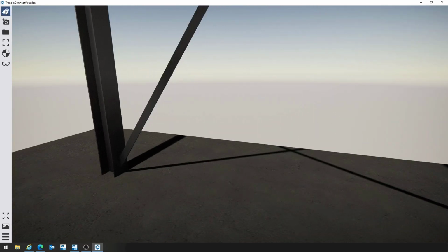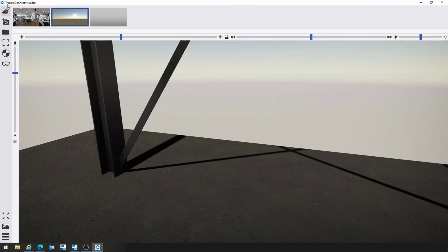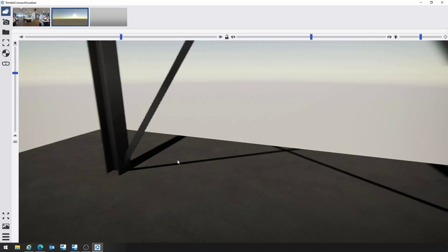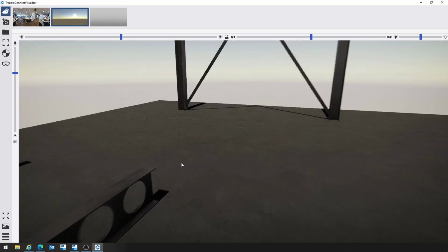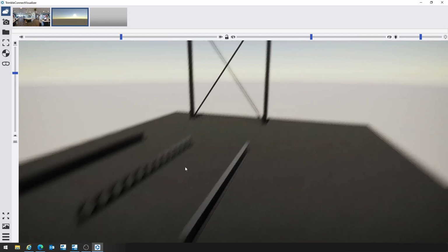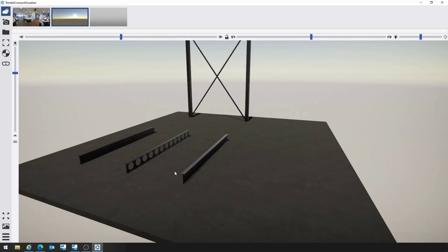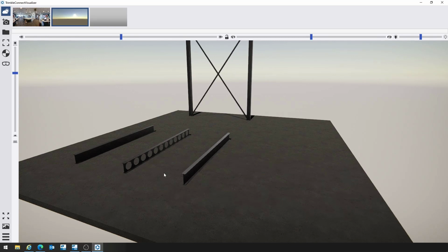The sun position is controlled up in the top left hand corner here with a picture of the sun and the clouds, and then you've got different options such as the position in the sky sort of moving around, and also on the left here the height of the sun, sort of sunset to midday with it being straight above. So I'll just quickly show what that looks like as you adjust each one of these, and then we can tie that in with a screenshot in different places and then create sort of a slideshow effect from that.